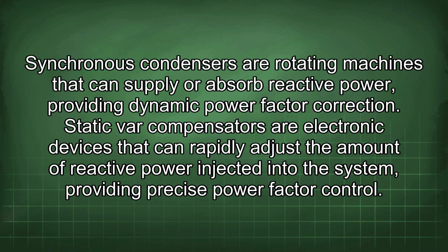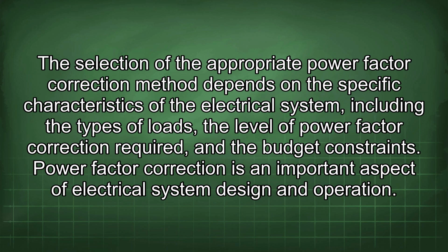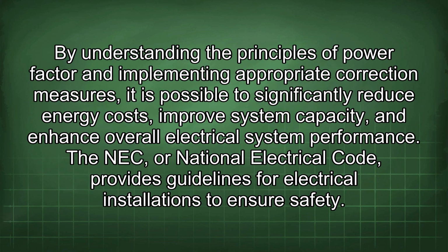Static VAR compensators are electronic devices that can rapidly adjust the amount of reactive power injected into the system, providing precise power factor control. The selection of the appropriate power factor correction method depends on the specific characteristics of the electrical system, including the types of loads, the level of power factor correction required, and the budget constraints. Power factor correction is an important aspect of electrical system design and operation. By understanding the principles of power factor and implementing appropriate correction measures, it is possible to significantly reduce energy costs, improve system capacity, and enhance overall electrical system performance.